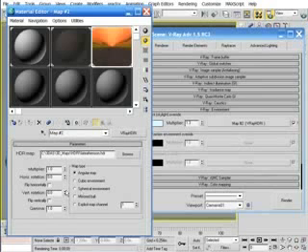First, you can choose how this HDRI is to be mapped around your scene, and this is the most important part of the interface to get right, because different HDRIs have to be mapped differently, otherwise you're sure to get strange results. So let's look at each mapping type so that you know exactly how to handle each type of HDRI available. Probably the most common mapping type and the most simple to visualize in your mind is the spherical environment mapping type.